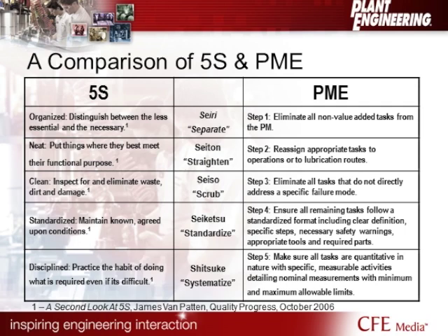If they're walking past a gauge and we can take the time to color code that gauge, very quickly they can take a look and see, is it within spec? And if it's not, then they would issue a work order through the CMMS or the EAM. This then takes that step away from the maintenance craftsman who may be coming all the way from another part of the facility just to check that gauge as part of a PM.